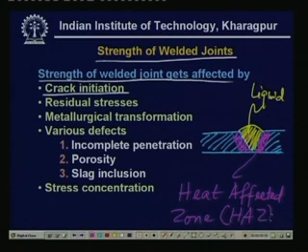This is very important because here lots of complications occur. The metallurgical transformation takes place in these locations. So this is the heat affected zone and this is the non heat affected zone, that is the original metal. This is the original part and this is the welded part, or maybe melted. Whenever it starts cooling, the cooling procedure is very much like in a casting. So all the defects of castings are present. So when it starts cooling, the procedure becomes very interesting.